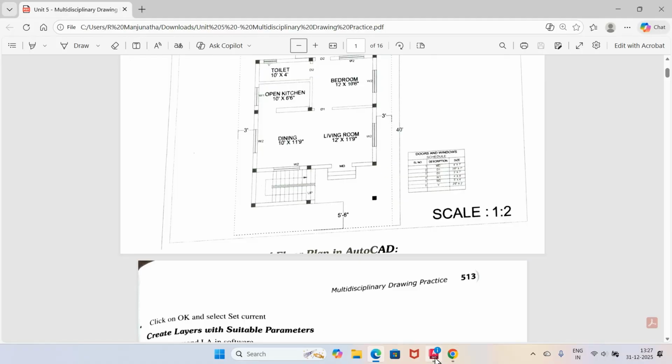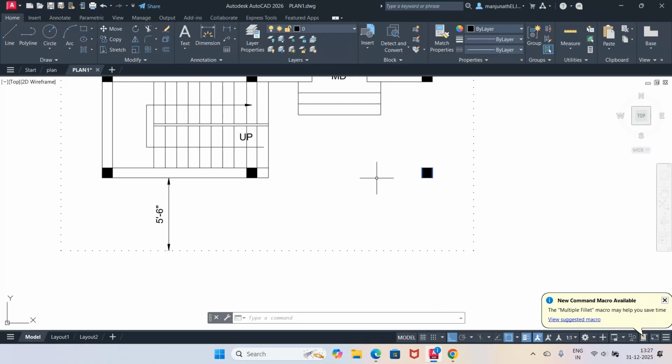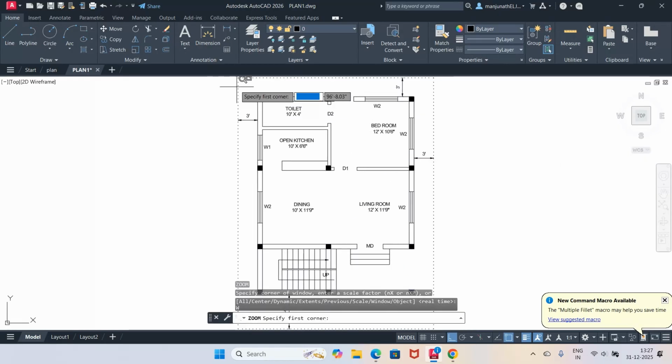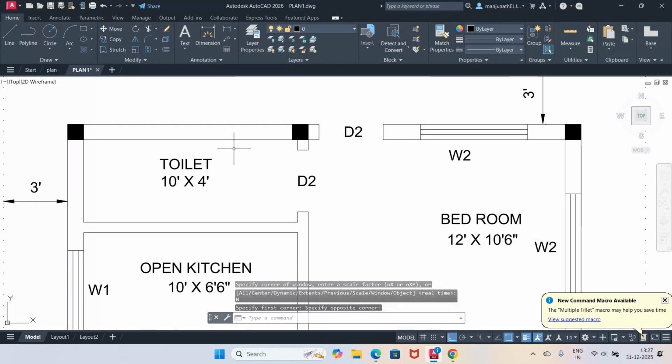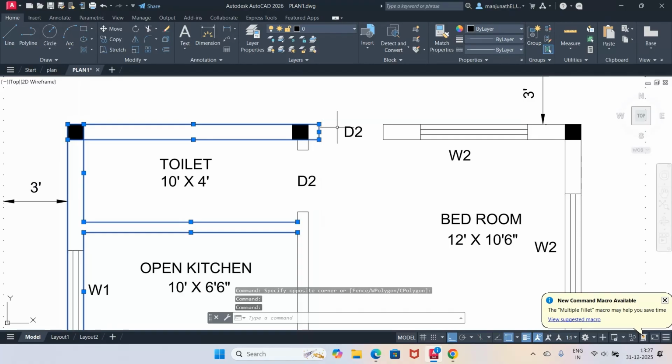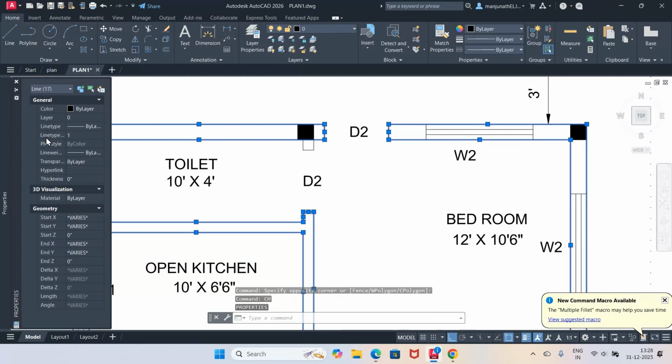But now what I want is to give the main walls. So still we have not cleared the wall thicknesses. These lines are still in layer 0. You just click on this. Click on these two and on this side. Similarly this line, then you take these two, then these two, then these two, select this, go to CH, go to layer, make these layers as walls.